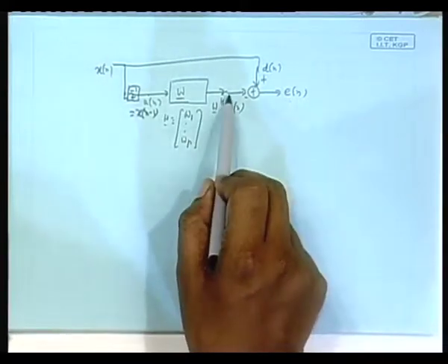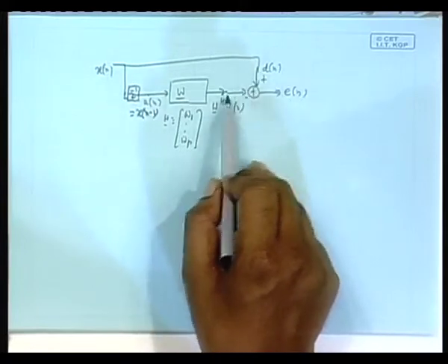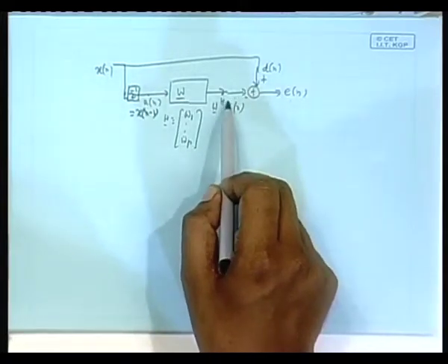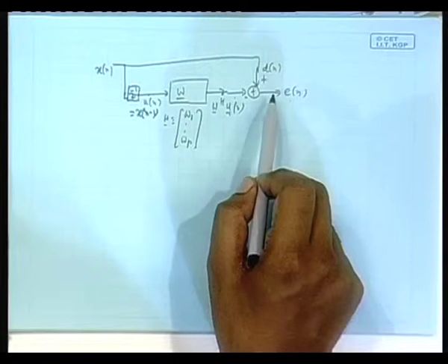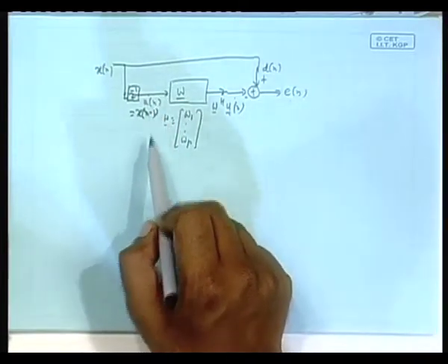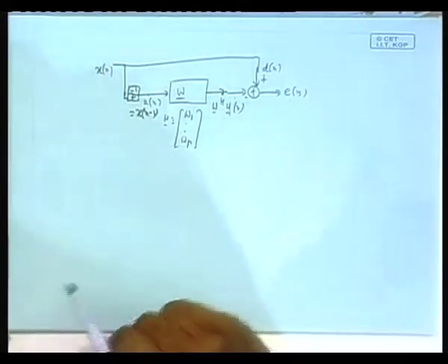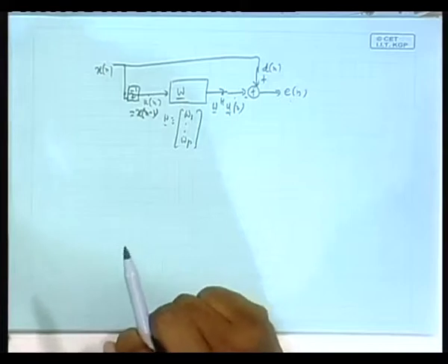The linear combination comes out here, which is the prediction. This is the best prediction, because this corresponds to orthogonal projection. The error is perpendicular, orthogonal to all these terms, xn minus 1, xn minus 2 up to xn minus p, and therefore the error has minimum norm square. Norm square means variance. Fine.